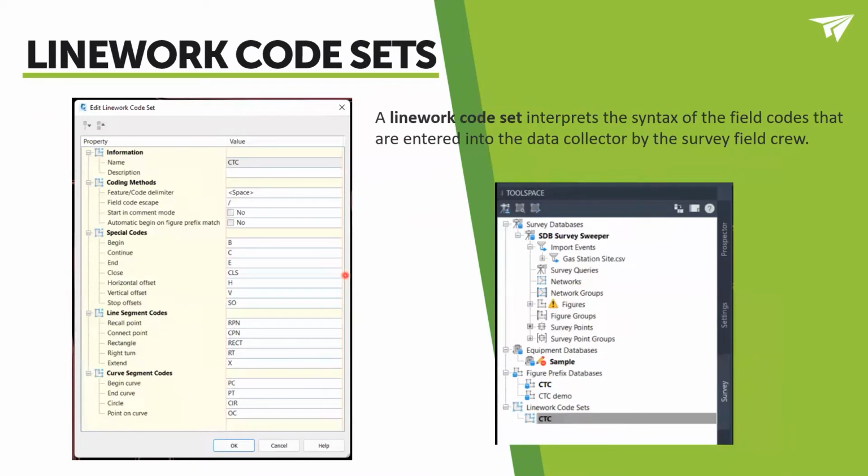Now, when it comes to your survey database and specifically our figures, we have a LINEWORK code set. When we bring in our survey figures, our points, they will be coded correctly. They will be coded per concrete, ground, etc. But they will have to have a suffix at the end of our points in order for them to string.